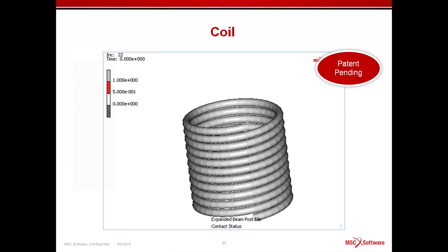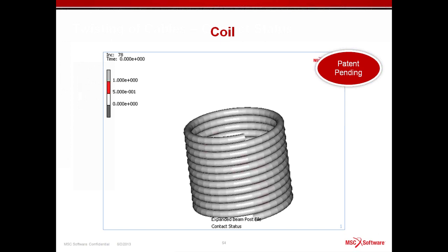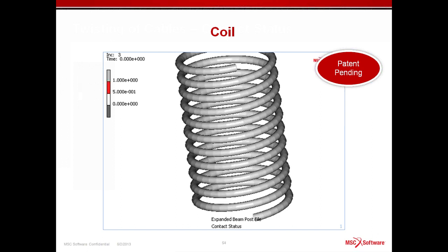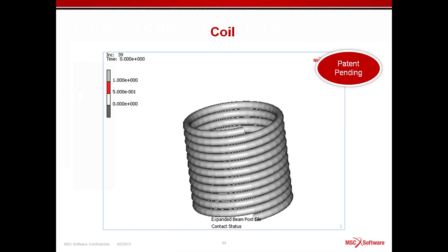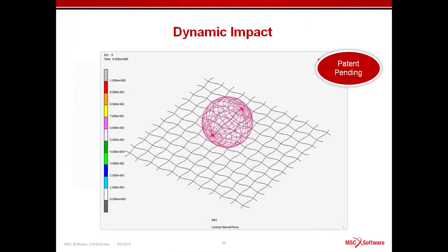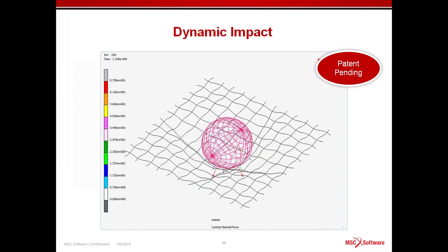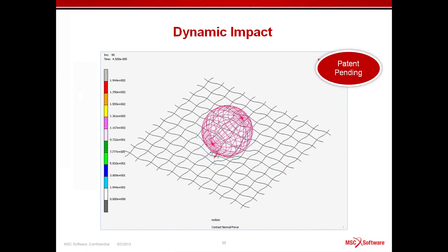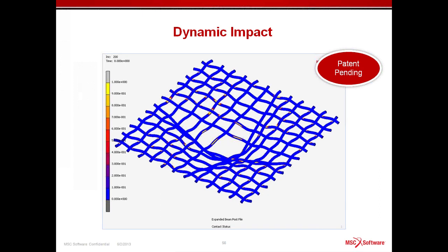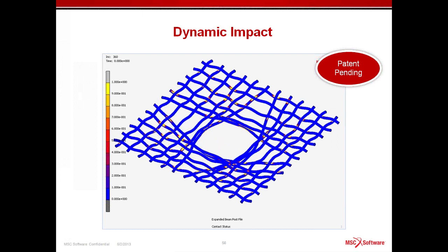And if we look at the 3D representation, this is what we see. So rather than having to do a 3D solid analysis with many more elements, we can do this at a reduced computational cost using beam elements, but still getting the accuracy. And this works in dynamic analysis as well. This would be a typical arrestor that you might use to catch something. And of course, the 3D representation of these beams and dynamic behavior as well.